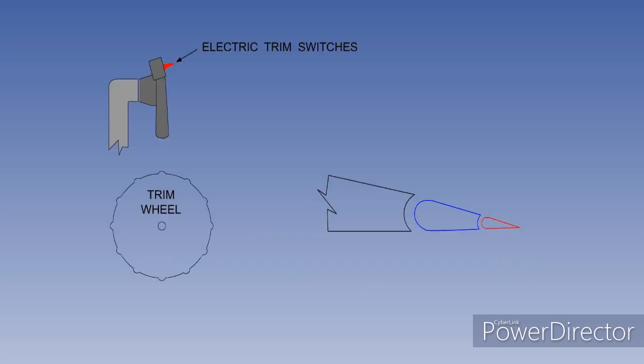To fly an aircraft in a steady state, climb, cruise or descent, the pilot must apply the stick force necessary to hold the aircraft in the required attitude. In other words, the pilot must hold the aircraft in a state of equilibrium, or trim. The stick force the pilot may need to apply to maintain equilibrium can be quite high, and all human beings find it impossible to maintain a constant stick force for more than a few seconds. Therefore, a means of reducing the stick force to zero is incorporated in all aircraft. This is known as trimming the aircraft.